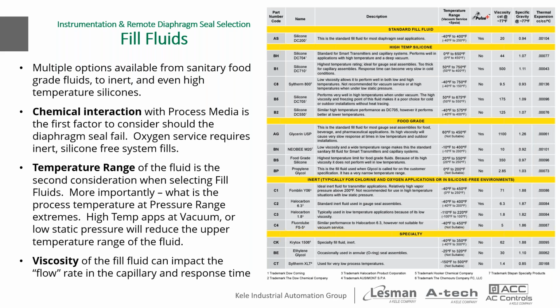Its viscosity, it does say 20 centistoke. It's actually closer to 10. Huge difference. You've got to be able to use that particular fill fluid, that glycerin, in the right application. You have to have large enough ID capillaries, and you really don't want it to be outside because that stuff gets cold. It's just not going to work. Simple things. Make sense?